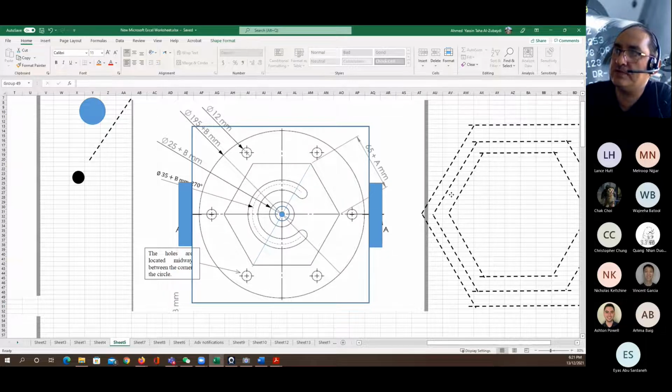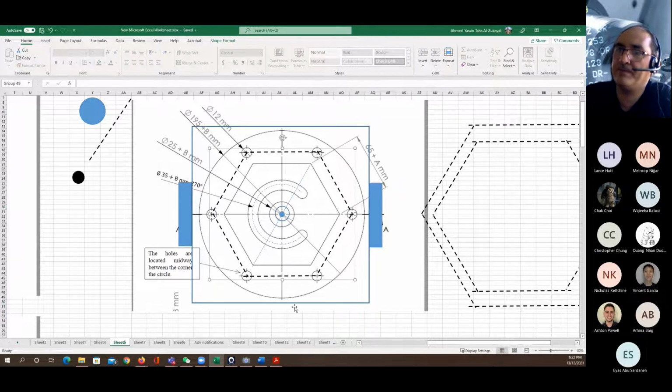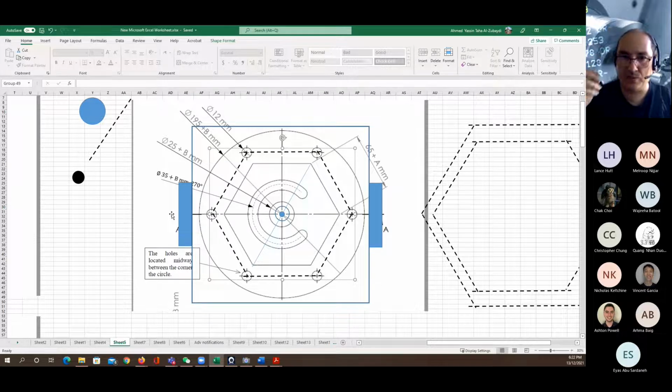So we will start first with the first line. We said that the offset here is going to be 6 millimeter. I can choose a bigger cutting tool so I can remove the material at a higher rate. Something like if I would like to paint a whole paper using this pen, which has a small ball pen, it's going to take me about 1 hour. If I'm going to use a marker, it's going to be done in 5 minutes because the marker is wider.